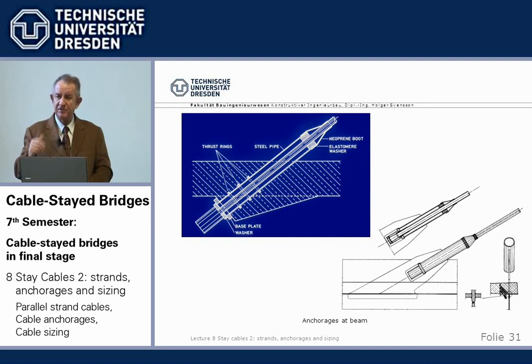This was first done for the Annacis Bridge in Canada, in British Columbia, by my friends Peter Buckland and Peter Taylor. The problem, of course, is the force transfer here. You can't weld it on top of the top flange. Then you have tension across the plate, and you get lamellar tearing, maybe through the thickness. Tension is much smaller than transverse.